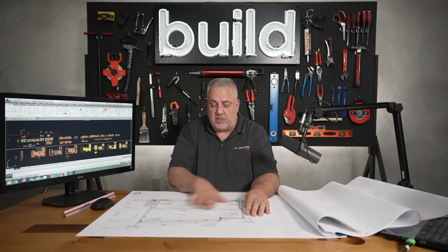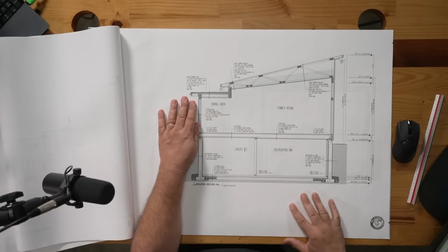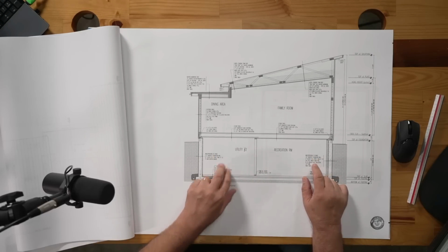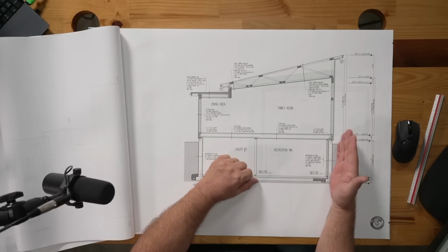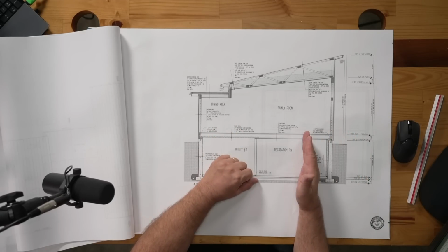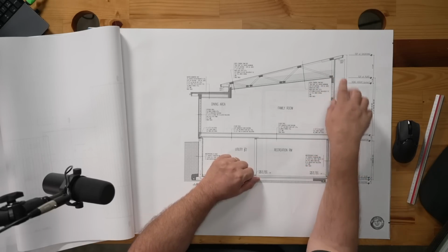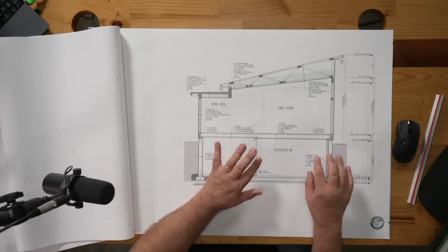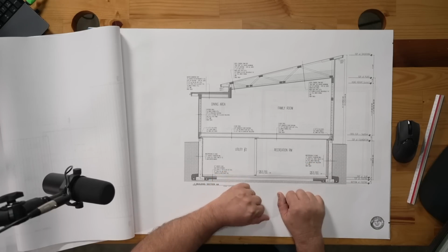Moving into the Series 30, you can see we have our building sections. The building sections give you some assembly writing here, which basically talks about what's happening from the outside of the wall through the inside of the wall, all the different aspects. We're going to have details of all of these specific areas cut out, and we'll have those finely dimensioned and tuned with exactly what materials we're going to be using in those spaces.